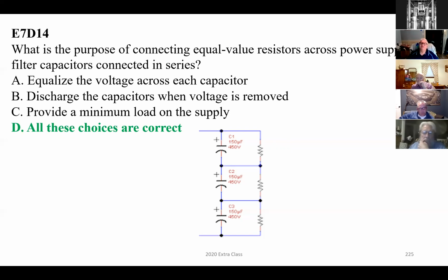I don't know if any of y'all have ever got bit by a capacitor, but they do bite. And that's another reason for the resistor across it. But if you're not sure whether it has a charge in any capacitor, the best thing is either take a small jumper wire or screwdriver or something, depending on what type of capacitor it is, and short it out, because you can really see a spark on some of these things when you short them out, or they do bite. And believe me, it will leave a burn on your fingers or wherever it hits.